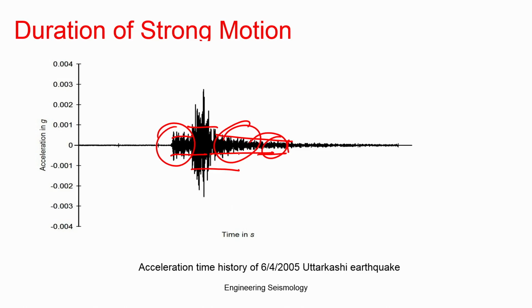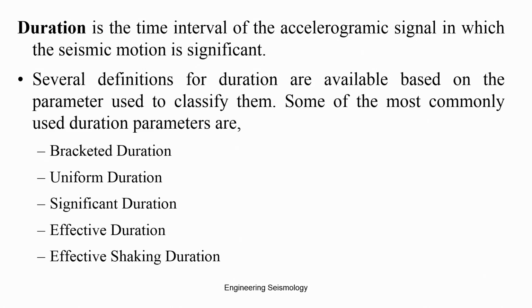This is the typical Uttarkashi earthquake. You can see that the P wave amplitude is similarly repeated many times, then the S wave amplitude, then again this is repeated. This kind of cumulative effect will result in a higher level of damage than a single peak value at short duration. That is the message we have to take from here. This will help you to design properly.